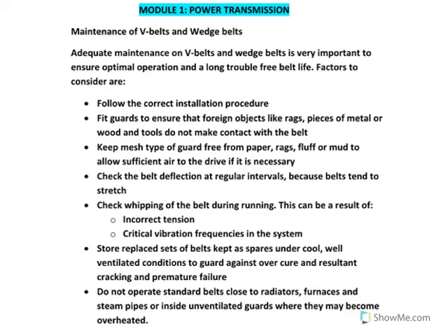Now, the next part says on the maintenance of wedge belts and V-belts. Adequate maintenance of V-belts or wedge belts is very important to ensure optimal operation and a long trouble-free life. Factors to consider are: follow the correct installation procedure, fit guards to ensure that foreign objects like rags, pieces of metal or wood and tools do not make contact with the belt, keep mesh type of guard free from paper, rags, fluff or mud to ensure sufficient air to the drive if necessary.